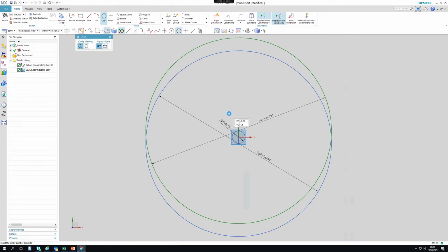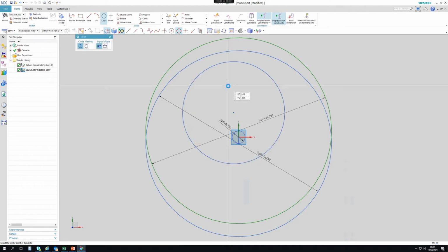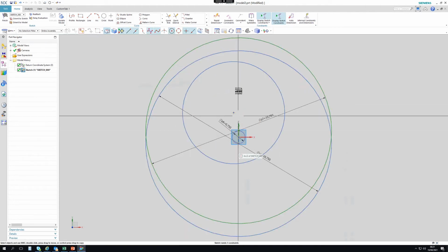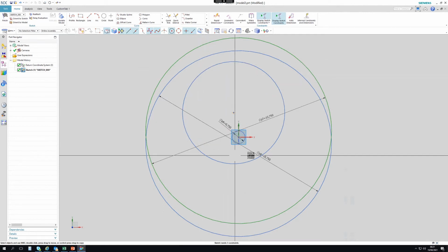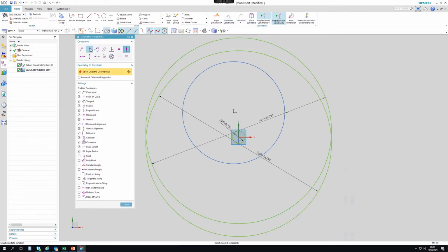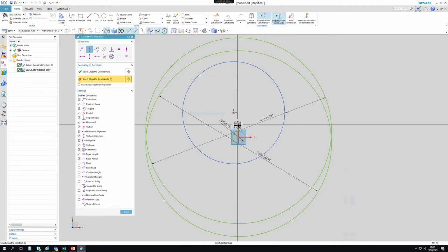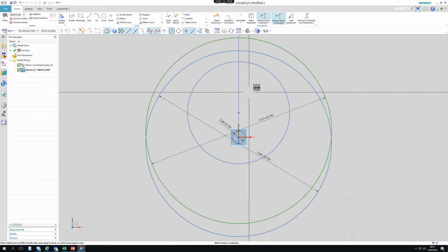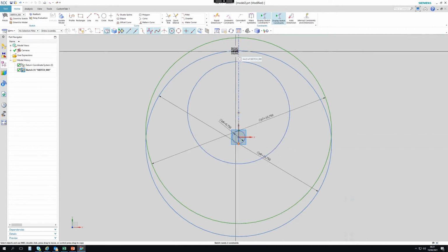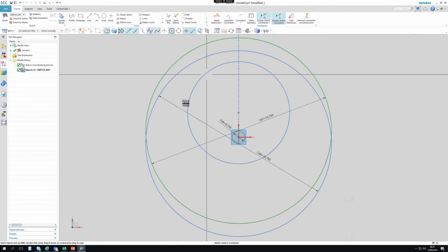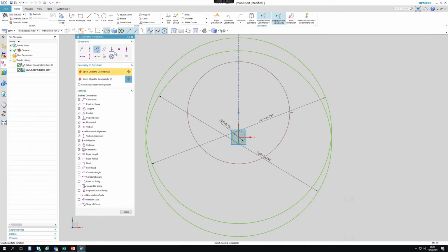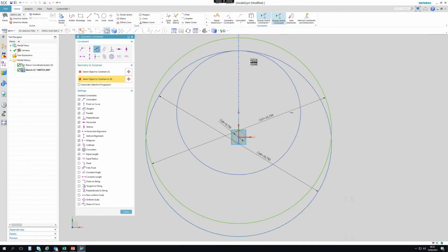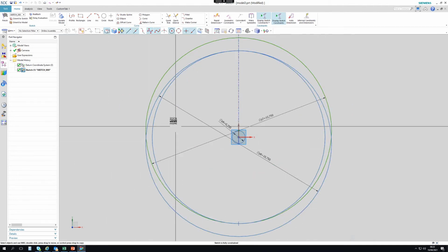Right, so let's draw a hole in somewhere. So this is going to be the bolt hole. Because we're working in the y-axis, we can put the centre of this circle on the y-axis, like so. And now what I need to do is make sure this circle touches this location and it touches this location, and that will give us the size of the bolt. There you go. So that is your bolt size.